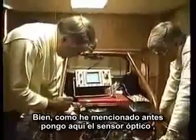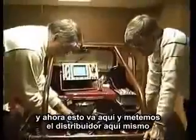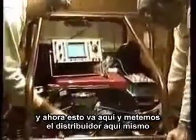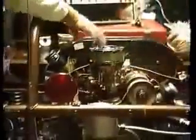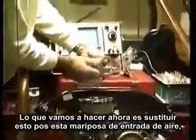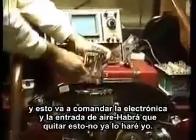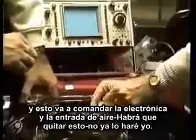Okay, now as you mentioned earlier, we'll take the light guides to sit here, all right? And then, boy, that went on pretty good, didn't it? That shield will go on top, and then of course we'll insert the rotor cap. And now we'll just go ahead and insert the distributor, see right here, okay? Now that'll be pretty good. Where's your lockdowns at? Oh, done. Now what we're going to do is that this is going to be replaced with this air gate, as you see right here. Okay, so that's going to regulate. I better turn it up right. And that'll regulate our air going in. Does this come off like this? Yeah, it'll take off.